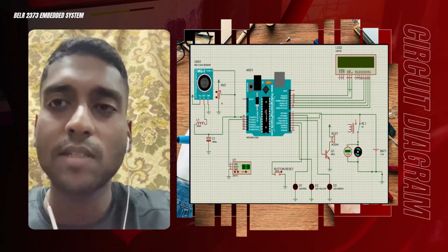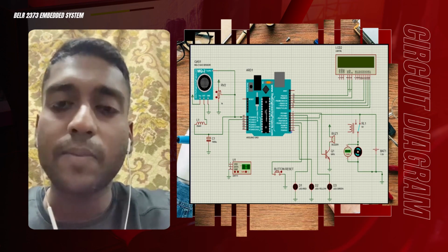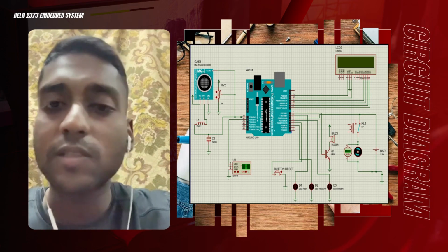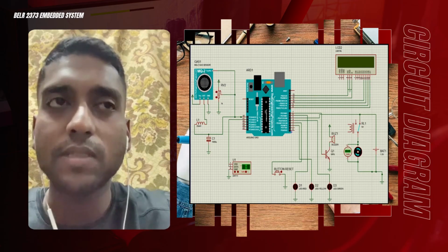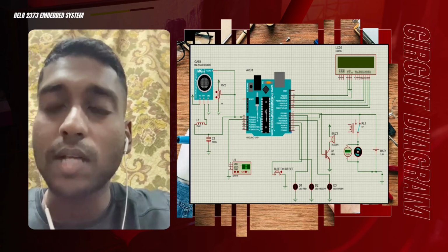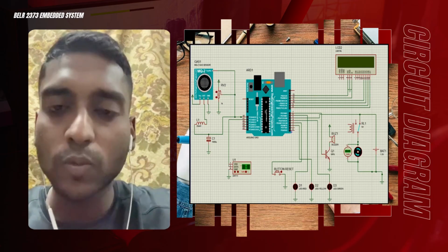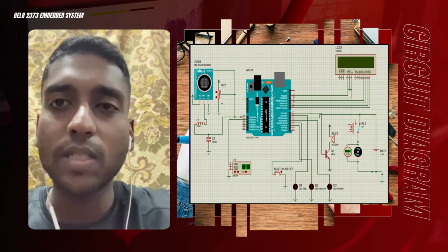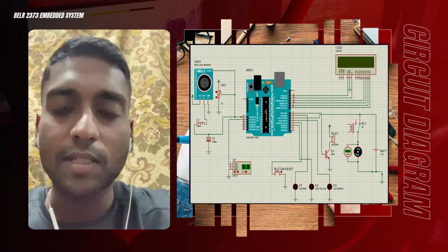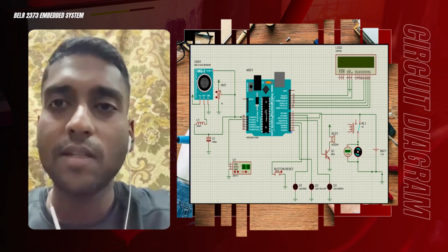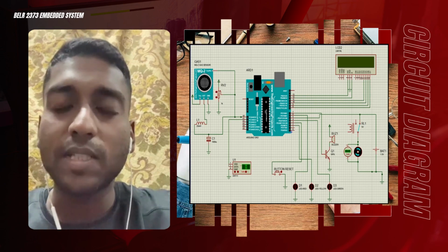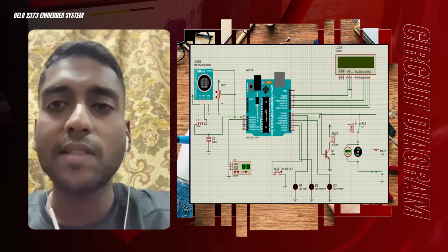The Arduino initializes all connected peripherals such as the LCD and the sensors, like the MQ-2 and the DHT11, and the IO pins. So they will be connected respectively. Then the LCD gets ready to display the sensor readings. That's the first part. Second, the sensor data reading.